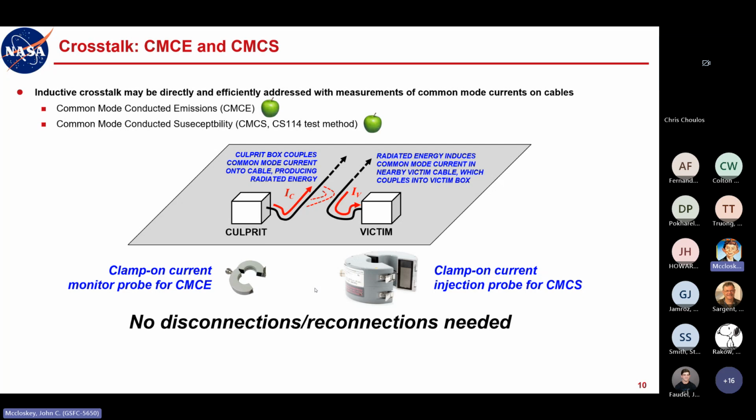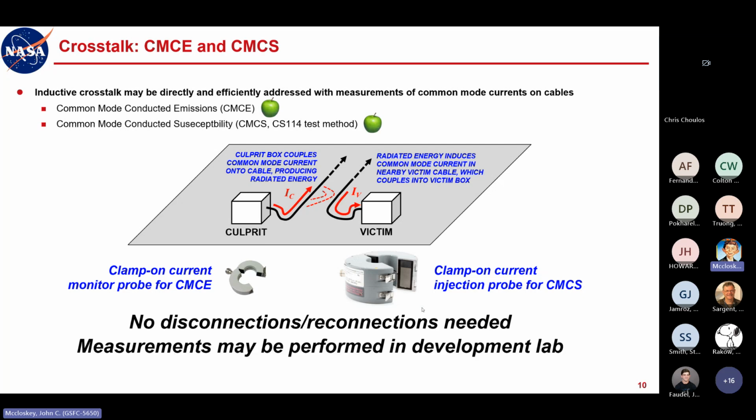And there are no disconnections or reconnections needed, no disruptions to your configuration. And measurements may be performed right in your development lab. And I always highly recommend you do these tests in your development lab before you bring your hardware to the EMI lab.